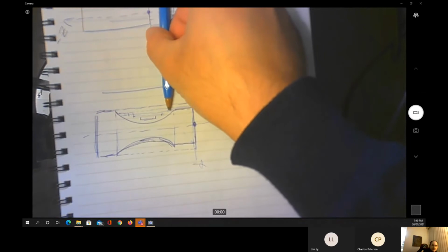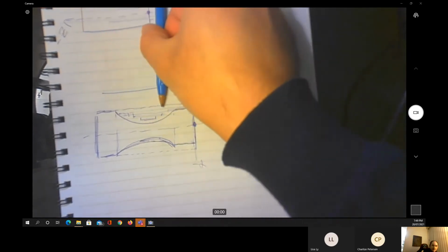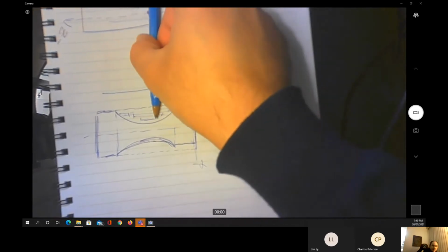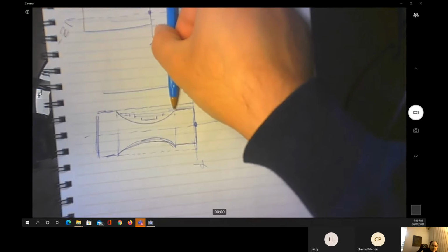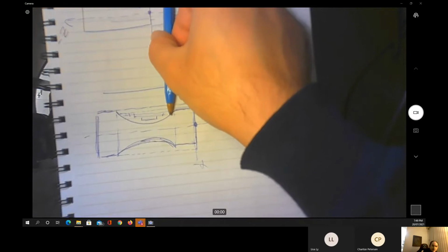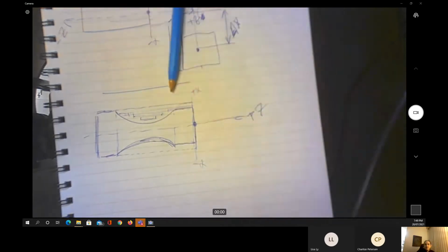We're going down and cutting this layer. Leaving, going back, go to this third depth, cut a layer, going up, back, going down, do another layer, then go up, going to this position, and starting here, then perform the cut of the G0 to make this cut.